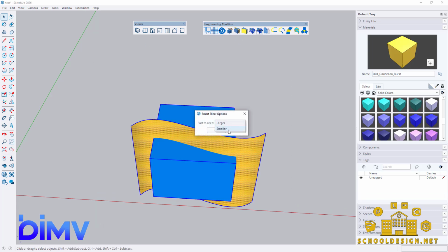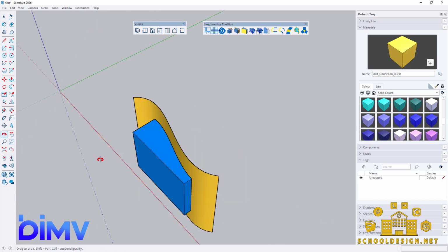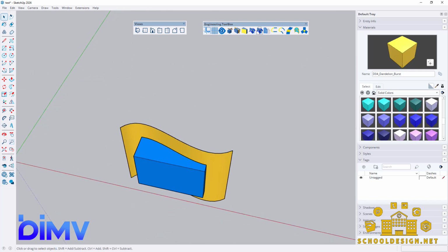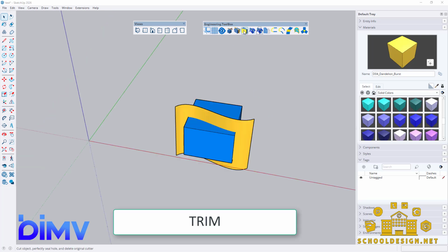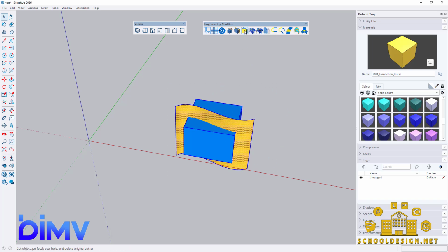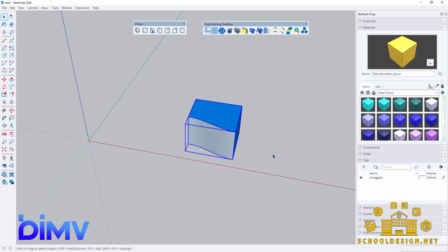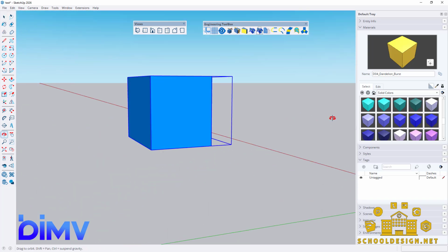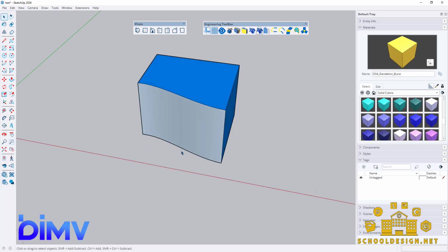If we select that we want the smaller one, then the other part will be completely removed here. The third option, as you can see, is cutting with the removal of the tool itself. So at this point we select the elements, we click OK. We want the large part to stay. We click OK, and it has already been cut right away with our surface selected.